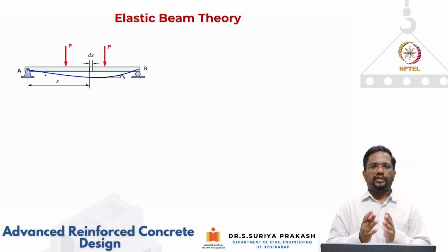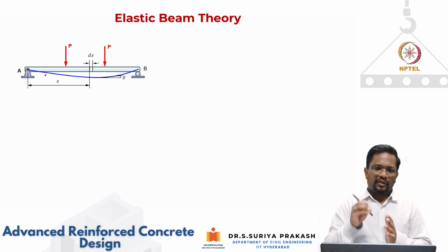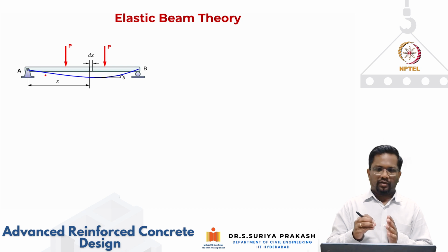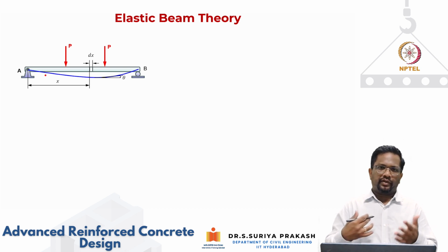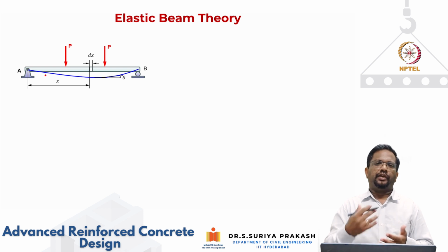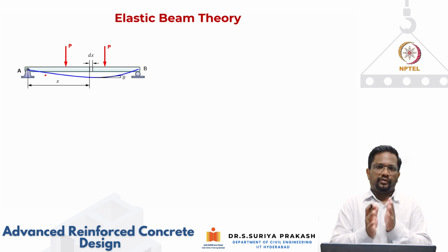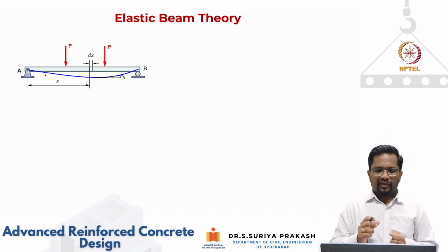that particular cross section is behaving with a certain reinforcement and concrete strength that we have assumed. So to compare the different sections, it is easy for us to compare so that we can compare apples to apples. So that is the reason we do moment curvature analysis.